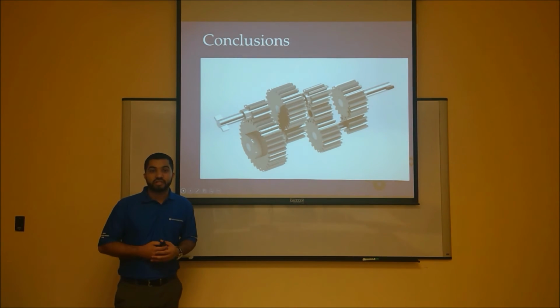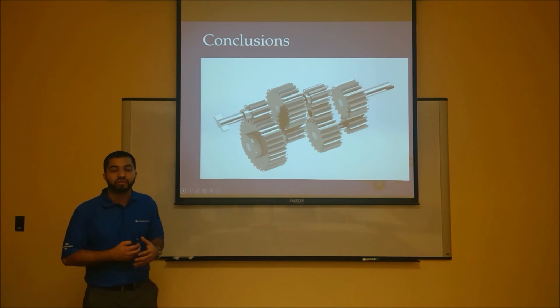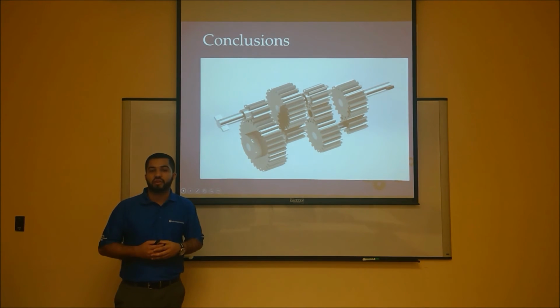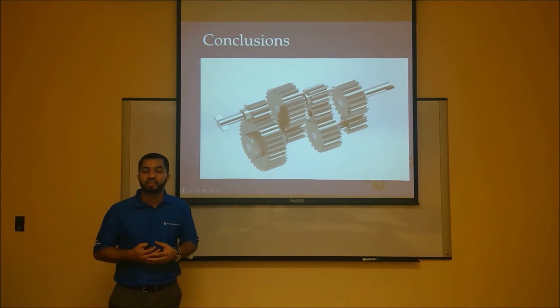Another thing that could be mentioned is that we could add magnetic plugs to the actual design in order to collect metal shavings, and that would also assist us in our maintenance program.